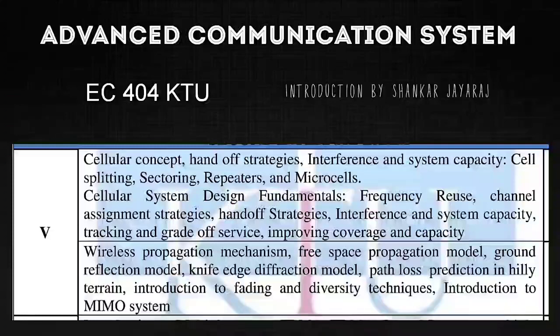Moving to the next section, we have cellular system design fundamentals, where we will see frequency reuse. That is a common terminology, and it is also asked in university. Frequency reuse is how effectively you can use the spectrum allocated to you, whether you can use a frequency right away or after a spatial distance.